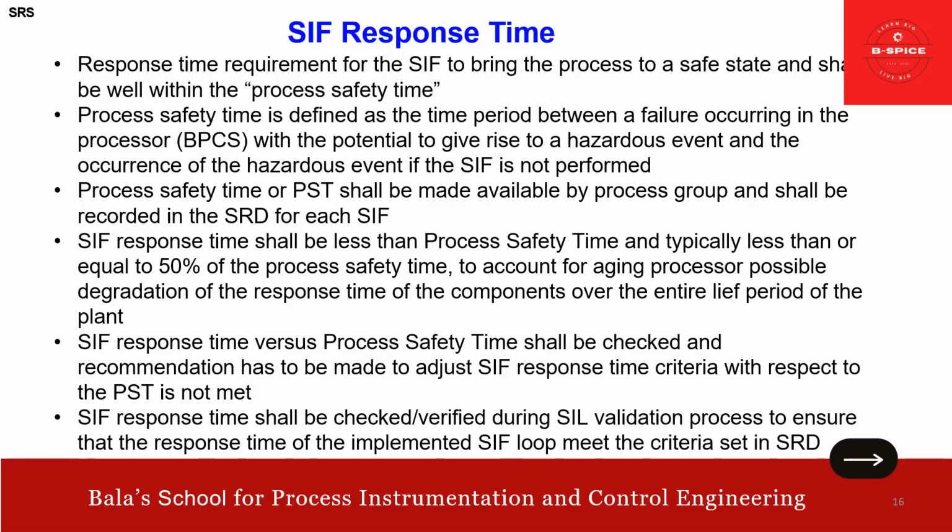SIF response time shall be checked and verified during the SIL validation process, to ensure that the response time of the implemented SIF loop meets the criteria set in the SRS. Okay, that is the point. So I hope you got some idea about the SIF response time.